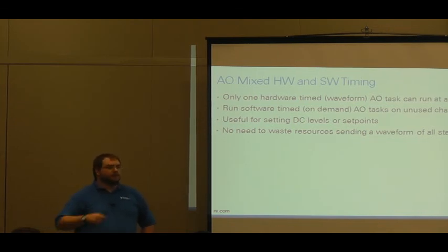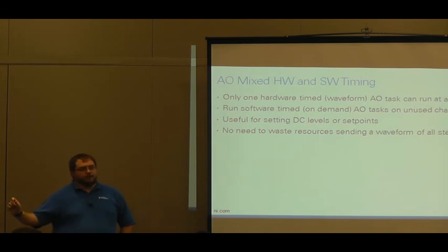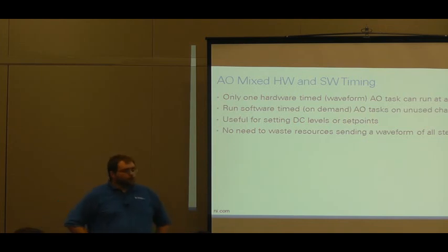So we're not constantly writing a waveform of a DC level. We can just update that on the fly when we need to update that one channel. So we don't waste resources calculating a channel of all 3 volts, and we don't need to waste bus traffic sending it down to our device. It also has the advantage that it will, in most cases, update more quickly. If I do a software timed update to my channel, that will happen within a couple milliseconds typically.